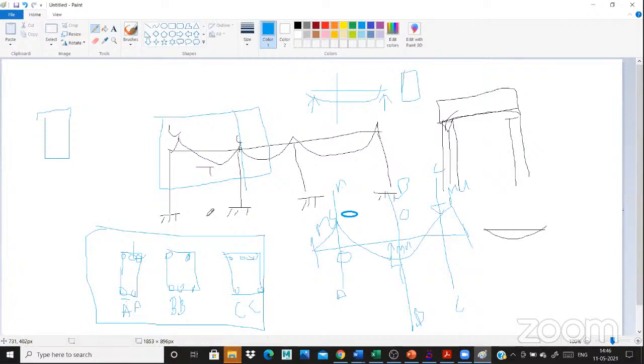Now understand. When you take a continuous beam, you take three conditions. That is the main reinforcement detailing. The compression zone is at the first end. At A, the compression will be high in moment and the tension is 0, so provide the minimum. Where the tension is high, I provide the tension reinforcement.